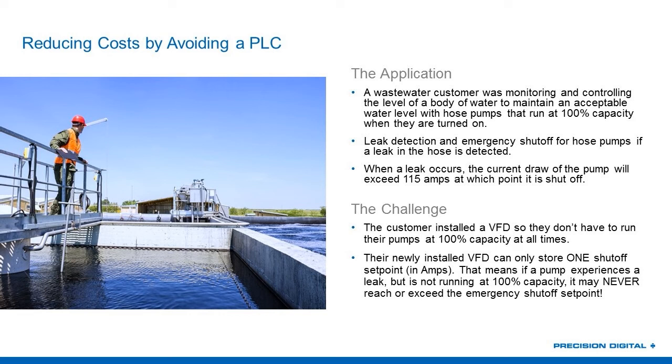That worked out great. But there was a problem. The reason why they used the VFDs was so they didn't have to run the pumps at 100%, right? But this 115 amp mark is based on the fact that the pumps would be running at 100% capacity.